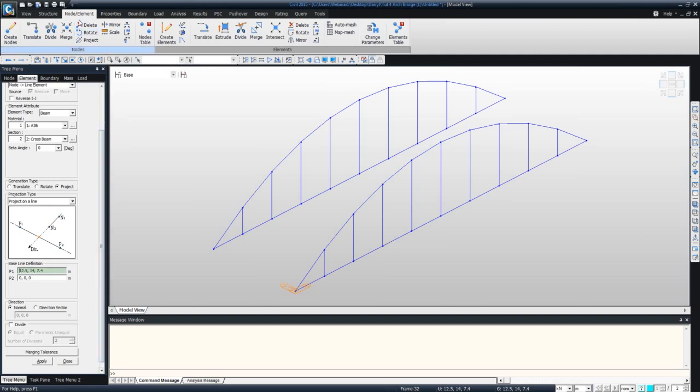Oh, and actually, before I select my baseline, I'll have to select my nodes first. So let me double check something quick. So 1 to 22. Okay, what I'm doing now is checking the node numbers. Once you create any node or element, it'll automatically be numbered. So I'm just checking the numbers here. Okay. So for the nodes that I want to select, it will be that top set there. So I'll select these individually.